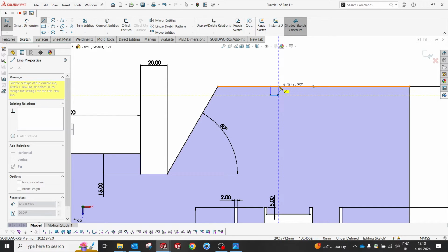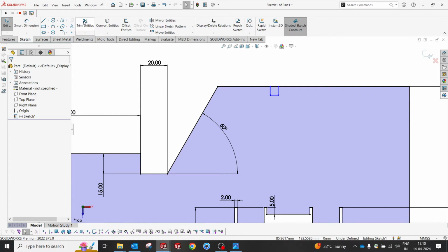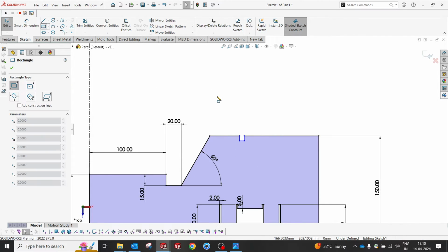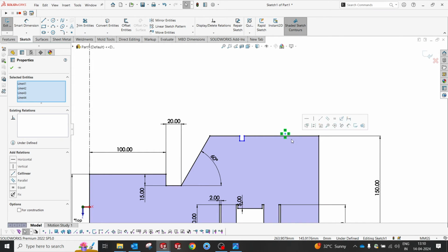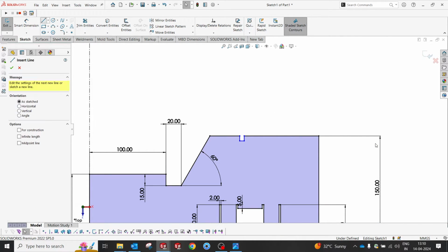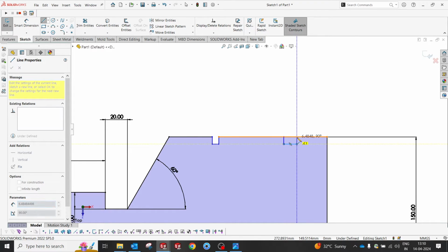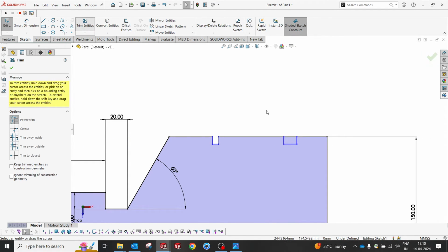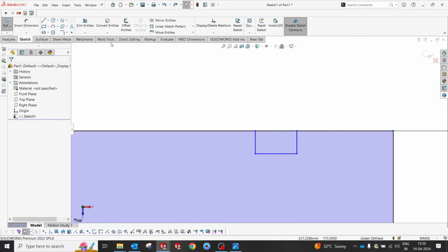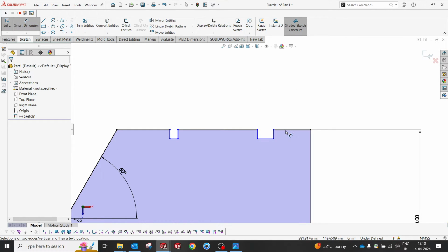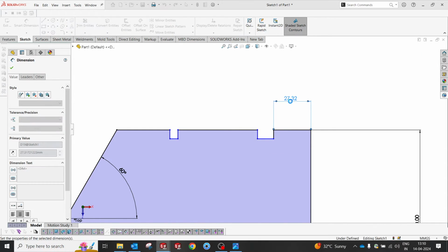Later we'll have one more relief. This can all be done while making an edge, while doing a bending edge. We can also give random height adjustments or a relief, but for now I'm going to create 45.